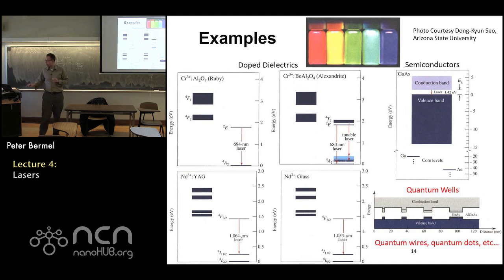And just an example of that is up here. This is a picture from a lab at Arizona State showing that if you take these semiconductors and make them into quantum dots with well-specified radii, they can have very strong transitions at targeted colors. So in principle you can do almost any color in the rainbow very easily. Of course, this is a really interesting direction if you need an alternative to rare earths for sharp laser transitions. And in principle, this can also be much more efficient than having a bunch of transitions like you have in a gallium arsenide laser.